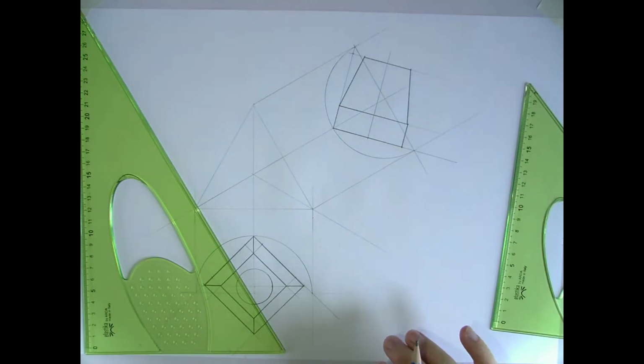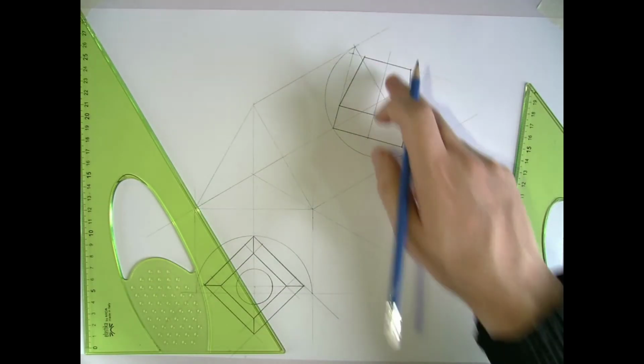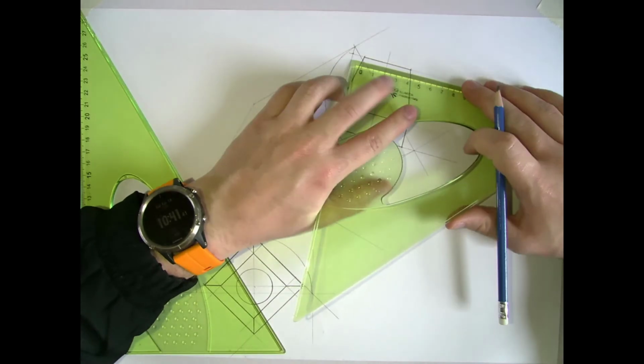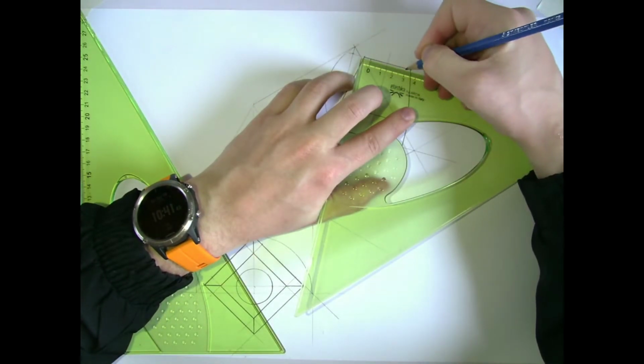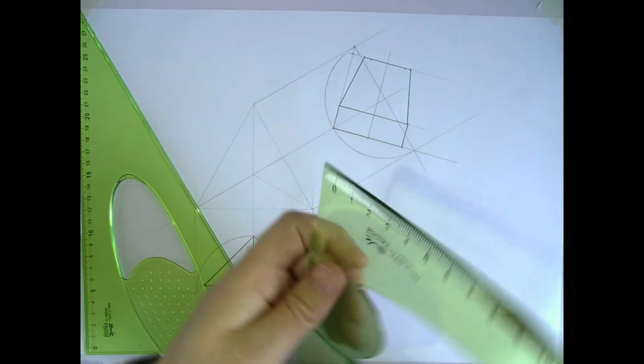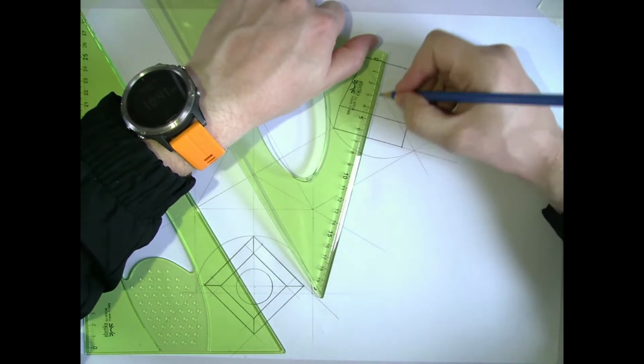Now that's almost it. We still need to put in the circular hole cut out of the center part here. So that was radius 15, so it'll be 15 now measured from either side, from the center. And that comes down a depth of 35.